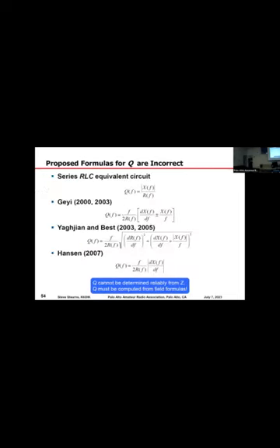I've seen these four formulas. I've also shown you that we can modify our antennas by putting structures into the antenna, either at the feed point in the form of lumped elements or transmission lines or electromagnetic structures that implement those lumped elements, because after all, a capacitor is an electromagnetic device, and so is an inductor.